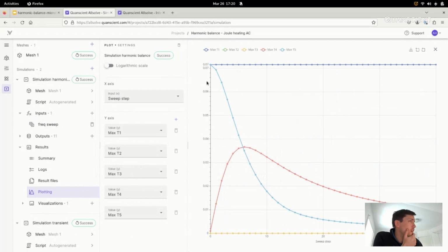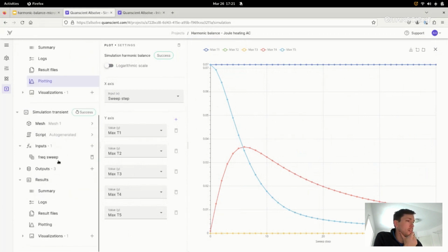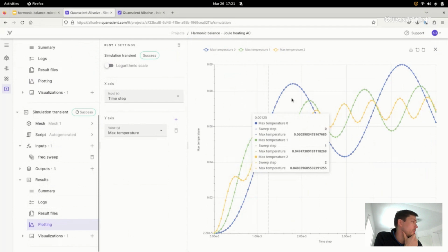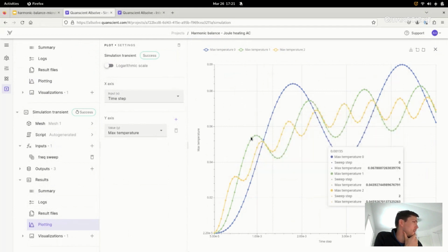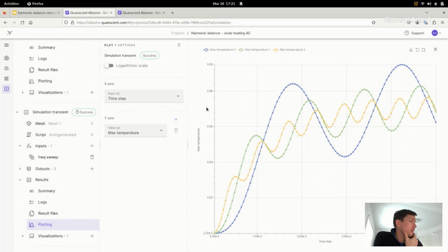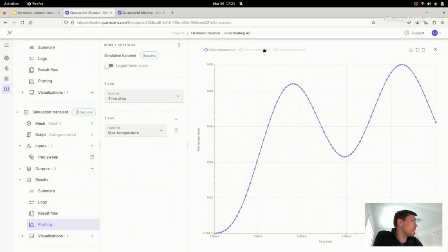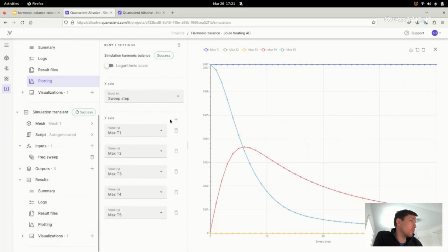And what you can see is that you have the constant heating, which is on harmonic T1. It's this part. This is around 71 millikelvin, and this matches actually the steady state value that you get here in the transient resolution. So you can see that it kind of settles at something that is close to 70 millikelvin, and this matches very well. And you can also see that as the frequency increases, the swing around the static heating decreases actually. So the blue curve is the lowest frequency, and then this one is higher frequency, and even higher frequency, the swing obviously decreases.